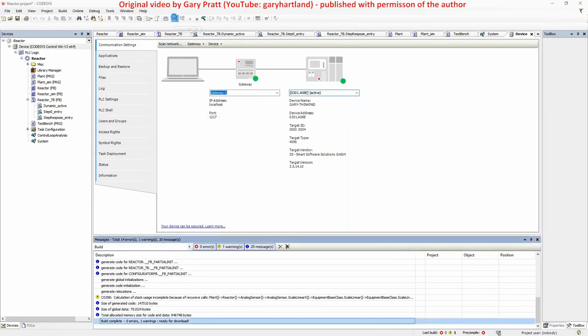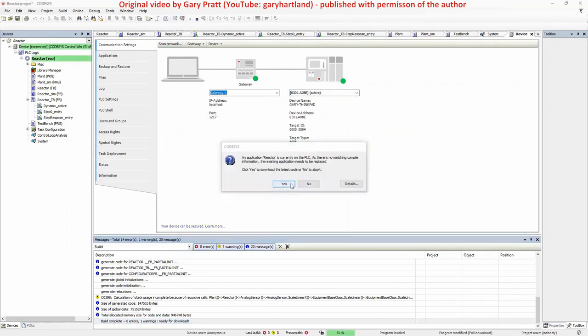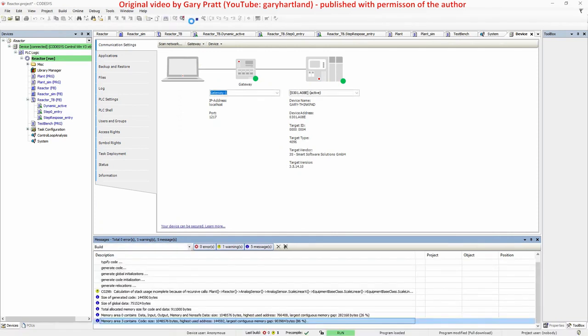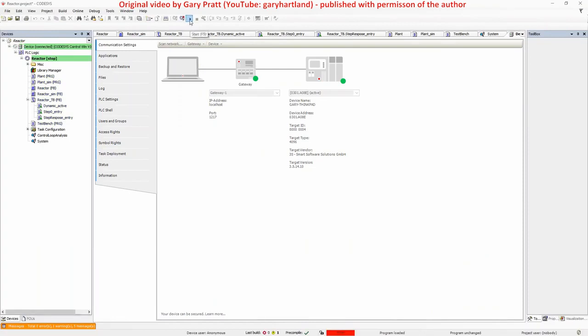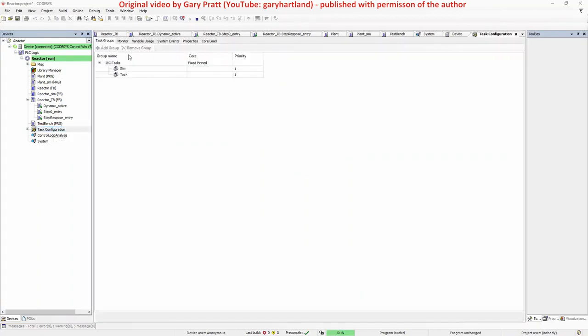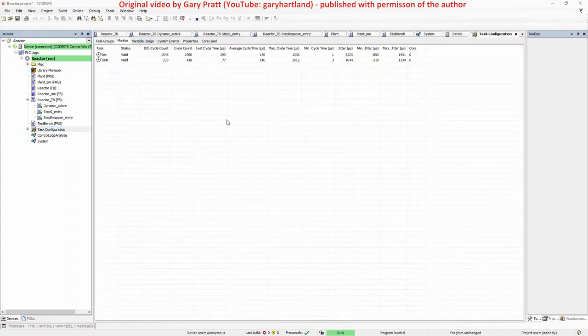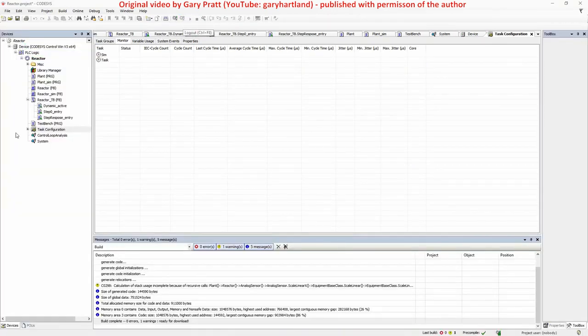The independent soft PLC is exactly the same runtime which is on any PLC that supports CODESYS. Using this, we can see what the performance will be if we deploy this project to a PLC with similar CPU hardware. To do this, we open up the Task Manager and look at its Monitor tab to see the statistics for the cycle time of the project. Notice that even though we are running second-order PIDs on 100 tanks, we are only using a couple hundred microseconds of CPU time. This really shows the power of compiled code under CODESYS with its custom compilers versus the interpreted code that many of its competitors use.